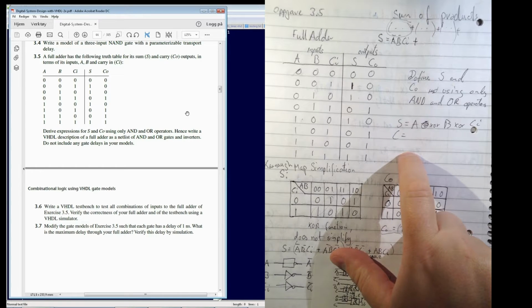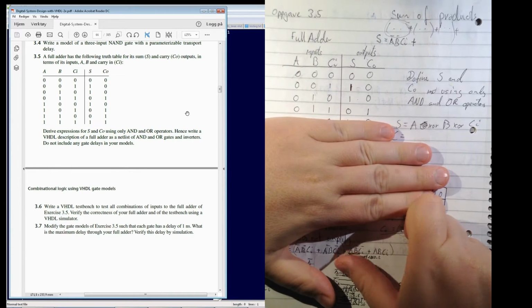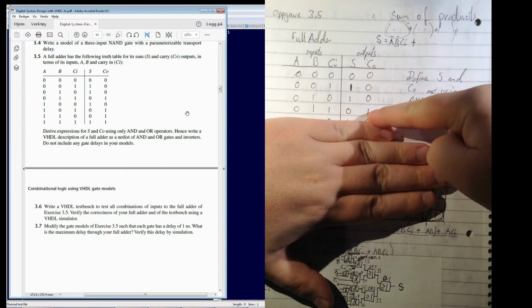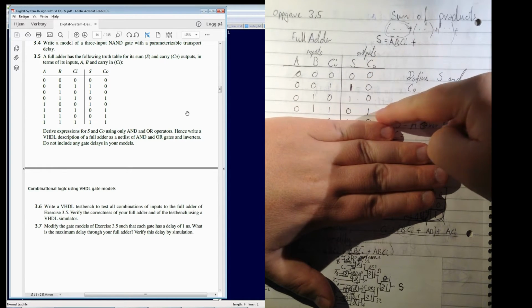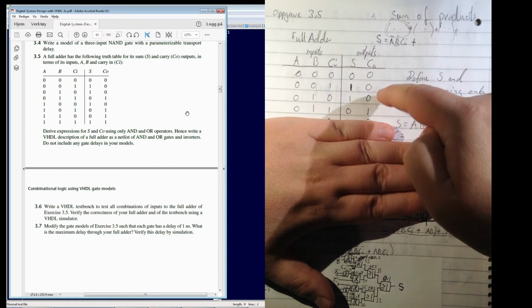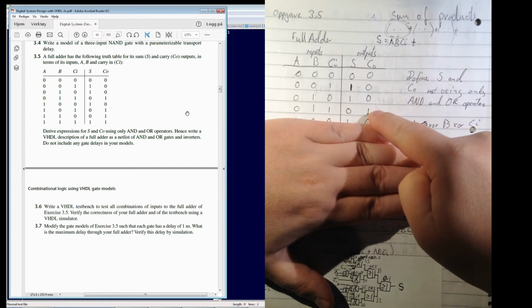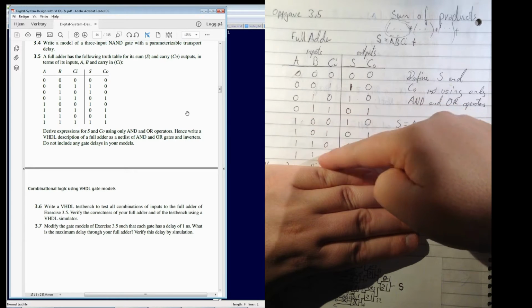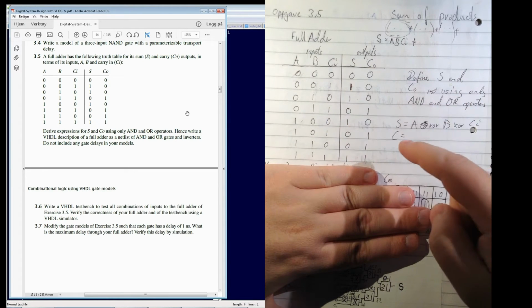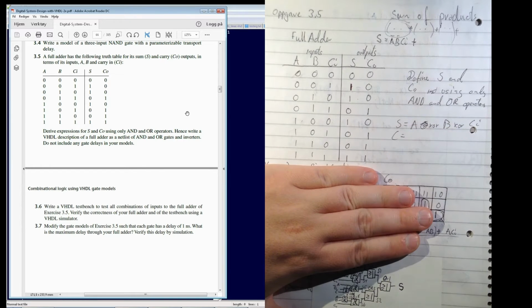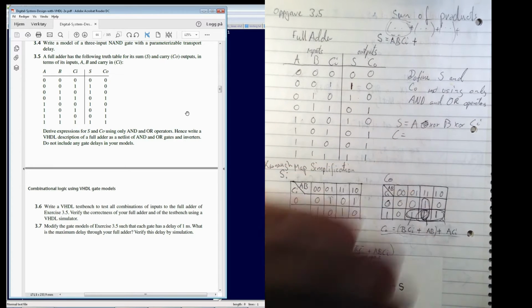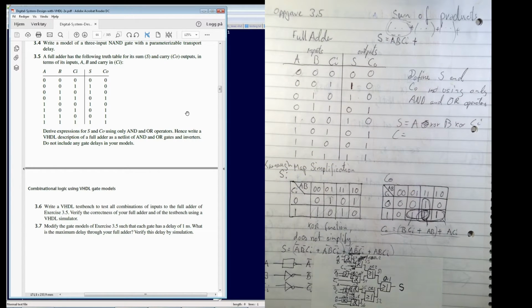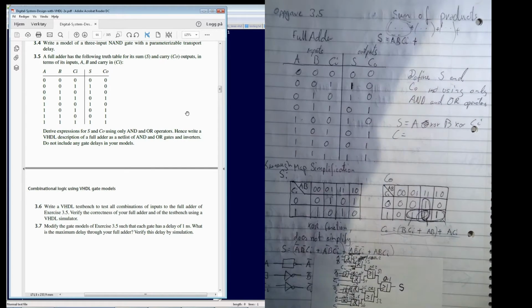and for carry you can divide the table in two and say, okay, if A is 0, then we have an AND gate. You can see in the truth table that this is the pattern for an AND gate, because both of them, B and CI, have to be on to get CO high, and then you can look at only these 4 last lines. When A is high, you can see that we have an OR gate. So only one needs to be high, or 2, for it to be high. So that's what I'm doing in the test bench to test the model you're going to make in this exercise